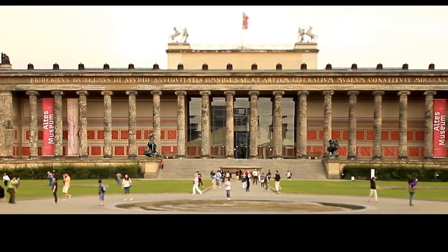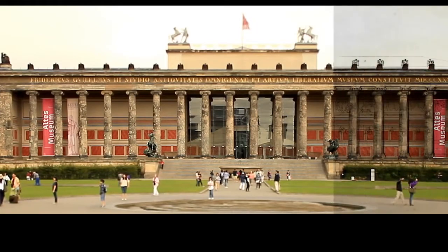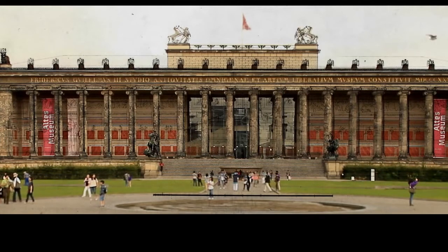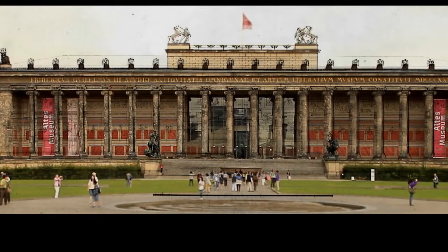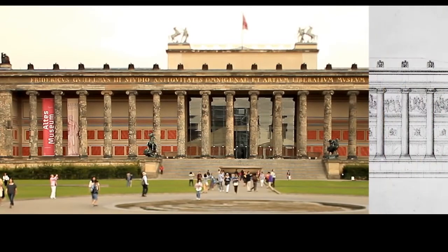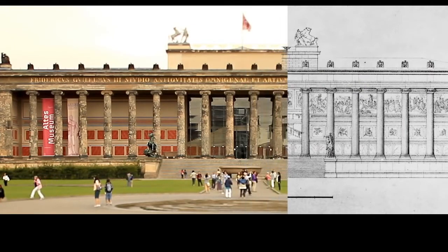A row of columns supporting an entablature, called a colonnade, is often used to define the public face or facade of a building, especially one that fronts on a major civic space. A colonnaded facade can be penetrated easily for entry, offers a degree of shelter from the elements, and forms a semi-transparent screen that unifies individual building forms behind it.